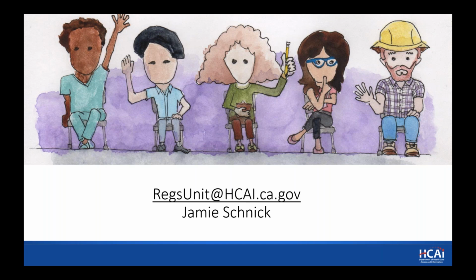So the answer is yes, you could have that installed, but when I said you should, it actually code requires that you provide protection to avoid leaks, if you have fire sprinkler pipe at 6 foot 6 inches above your equipment. Hope that answers the question.